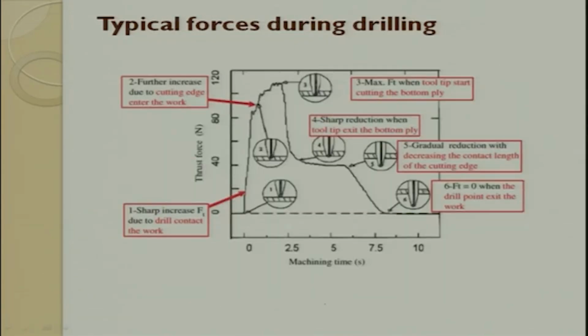This is another example which I have put. You can see the sharp increase is due to the drill coming in contact with the workpiece. Then a further increase is due to the cutting edge entering the workpiece. The third portion is the maximum force, when the tool tip starts cutting the bottom ply. This will be the maximum force.